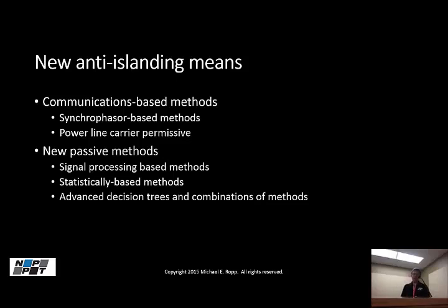My company has been working on a number of different synchrophasor-based methods, but the one that is kind of my favorite is we use the frequency that's measured by two phasor measurement units. One of them is outside the island. It's upstream on the system someplace. And then that PMU is broadcasting the frequency measurement downstream so that it can be received by the distributed generators. The DGs have their own PMU there on site. They receive the remote signal. They do their time alignment. Then they do some kind of a comparison to figure out what their status is relative to the rest of the grid.